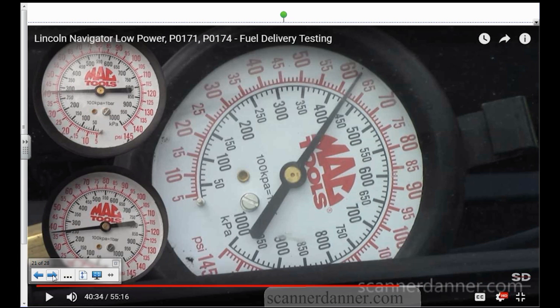I didn't like this though. I snapped the throttle and I noticed this. And in the video you'll hear me talk about it. What am I seeing? I'm seeing a pressure drop. It's very momentary. It does happen on the initial snap. I want to tell you guys about these returnless